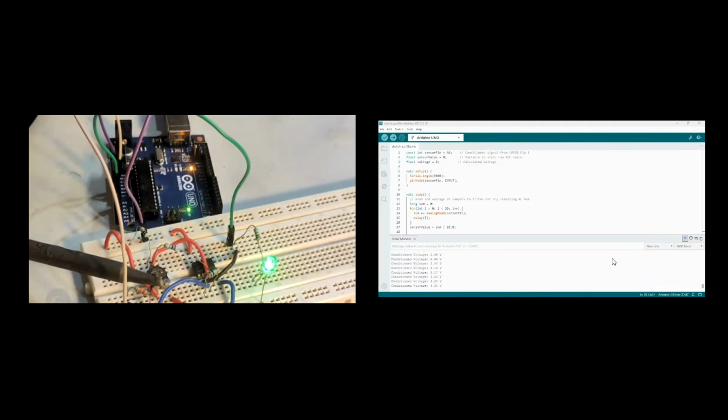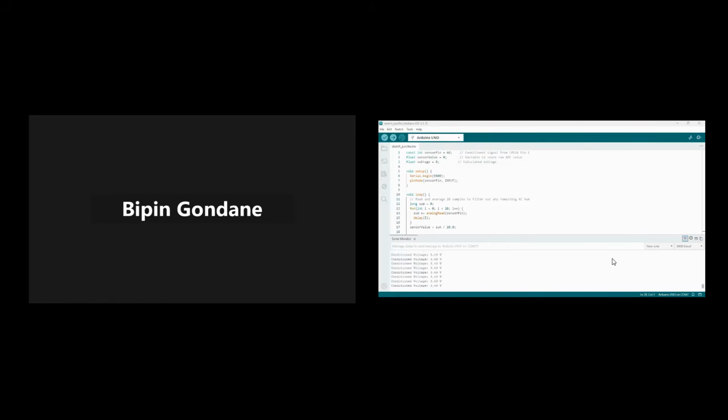So you can see here, it is gradually increasing. If we go up to the threshold, we can adjust it with the help of the Wheatstone bridge. We can adjust the voltage, how far it will go. So this is a very simple way of relating temperature to voltage. For the accuracy, and why we use this active signal conditioning in industries, I've removed the iron now, and gradually it will come down. Please watch that also.